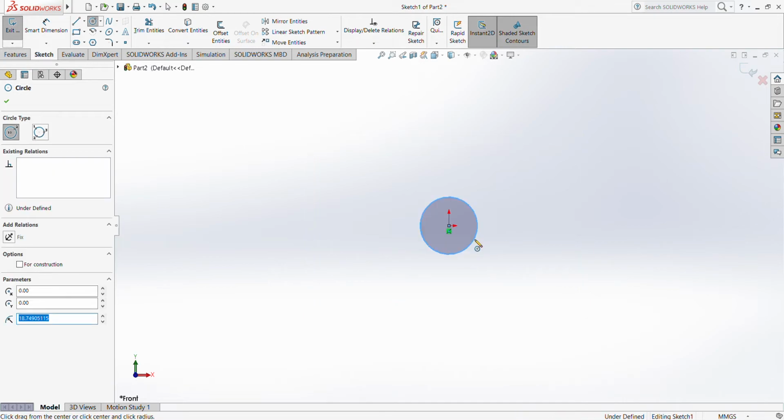And now for this one, the inner diameter of the last part was 2.2 inches. I want to make the outer diameter of this part 2 inches. So there's going to be a 0.2 inch overlap. So I'm going to start with this being 2 inches. For that, I just arbitrarily dragged it and stopped.